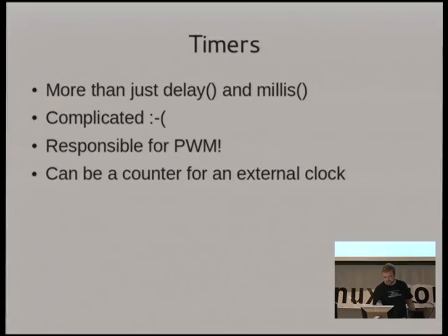One of the other things to note is that it can be accounted for an external clock. This is actually something that Bunny touched on in his presentation this morning. He talked about possibly being able to use the clock source from the incoming video signal to do something with his project. So this is something you can do with that. You can actually say, for this particular timer, I want to use an external clock, which might be, say, a 60 hertz clock or a 50 hertz clock to sync up with your incoming input signal.